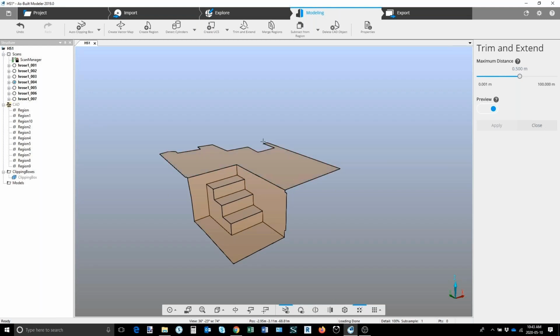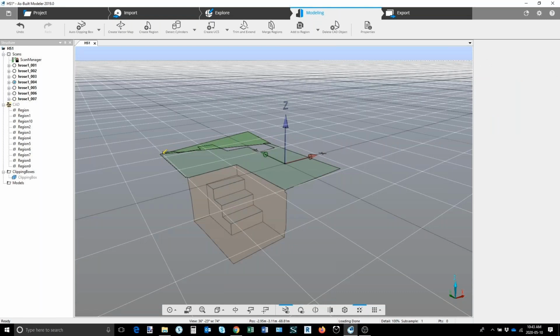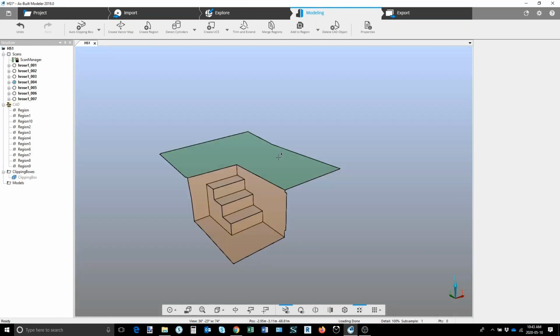On top of that, we have other editing tools, like we can add to the area that has been already extracted. This is a very nice feature because sometimes we have objects that create shadows on the point cloud, and literally we don't have a good amount of data, so we can use this function to add to our region, and just the opposite to that, we can subtract.